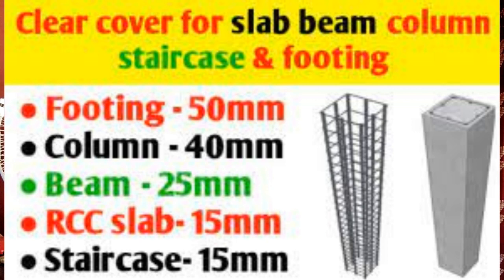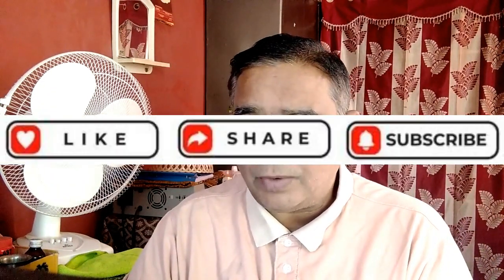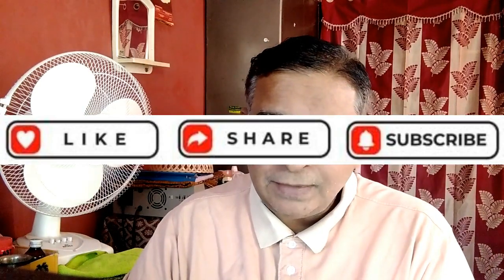Next point is, what is the purpose of flat slab? Flat slab is also known as beamless slab because it is supported directly by columns or caps. Here, the loads are transferred directly to the columns. The function of this type of slab is to provide a plane ceiling surface which will give the best diffusion of light.